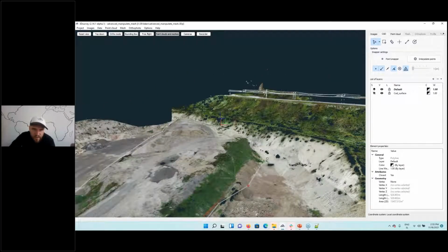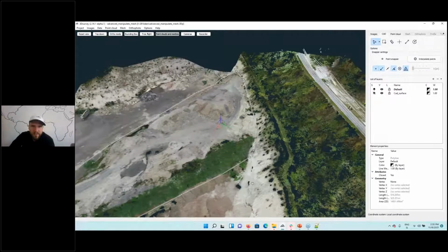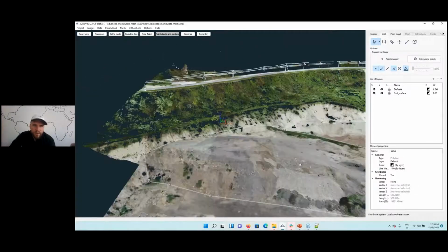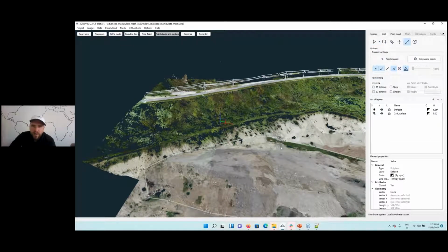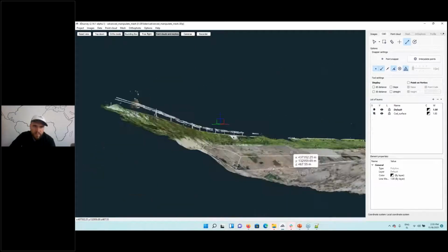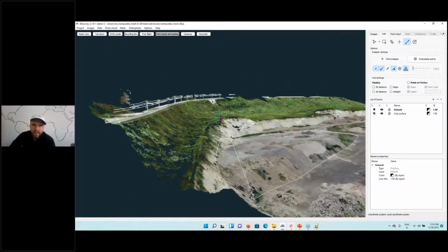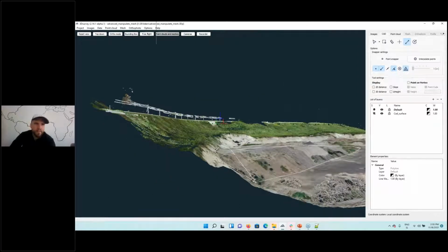Or actually this volume, it goes here actually. Like that. So here in this case, we will want to add a break line like so. Okay, and now to generate the bottom surface, we will just triangulate this data.